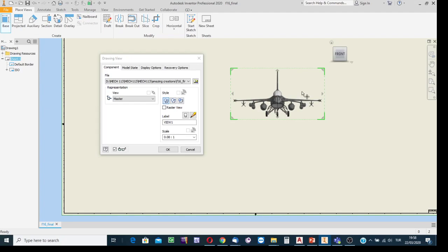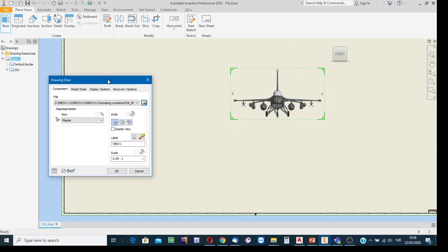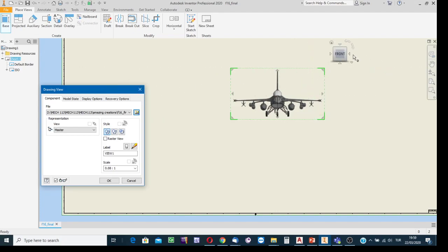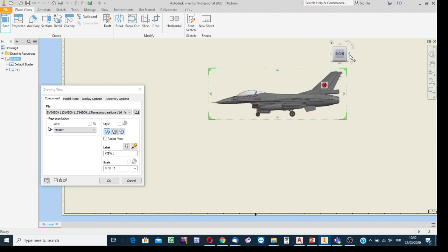I'm going to create the views, defining not this side but the other side as frontal. At the view creation stage, clicking on the arrows around the orientation cube can teach the software which side view is to be created as the base view. Click on this arrow and it rotates the model at the background about the vertical axis through 90 degrees.